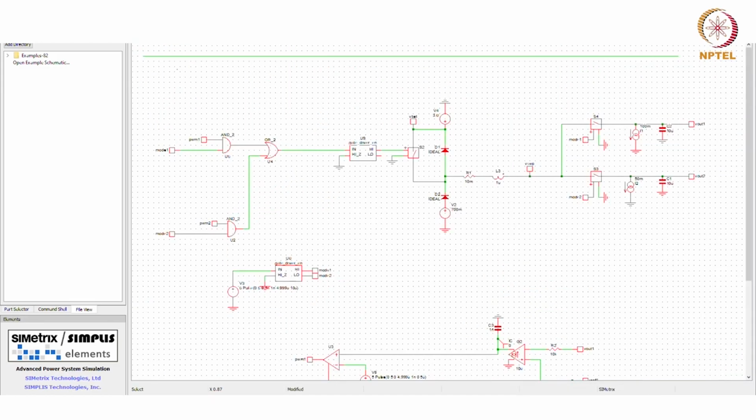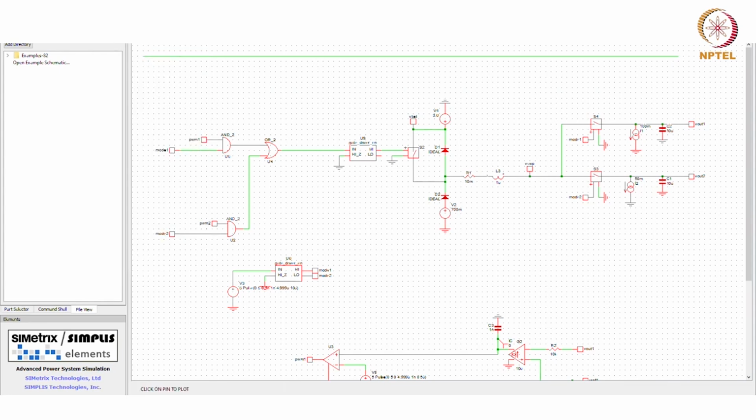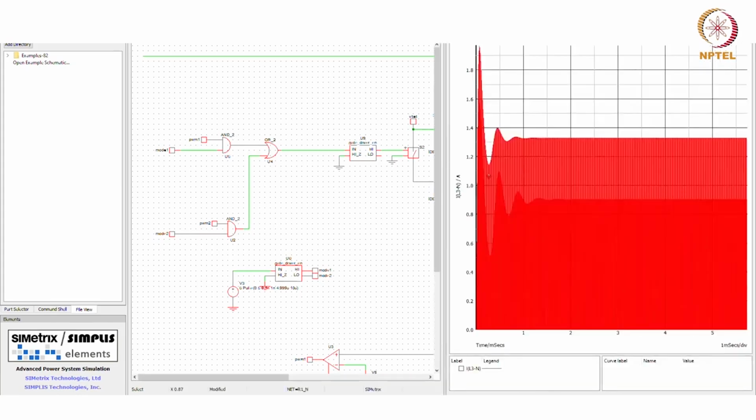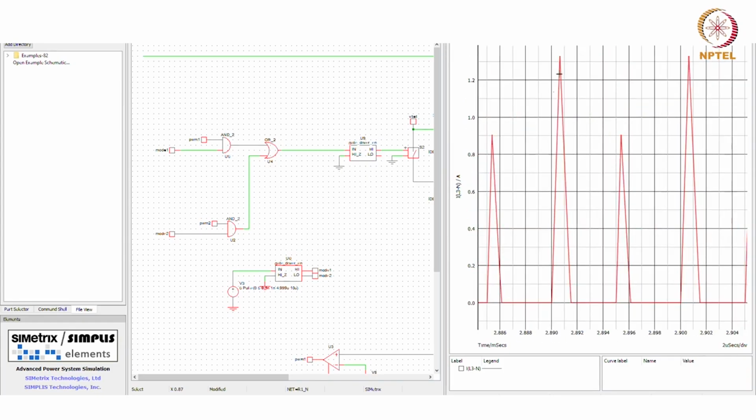Now let's see how the current looks. So in one cycle, the current should correspond to 100 milliamp, and in the other cycle it should be 50 milliamp. So this one has a lower current, so in one cycle you will see the peak current will be less compared to the other cycle, and you will see the difference here. See, inductor current. During this time you are turning on one switch, during this time you are turning on the other switch, and that's why you see this difference.